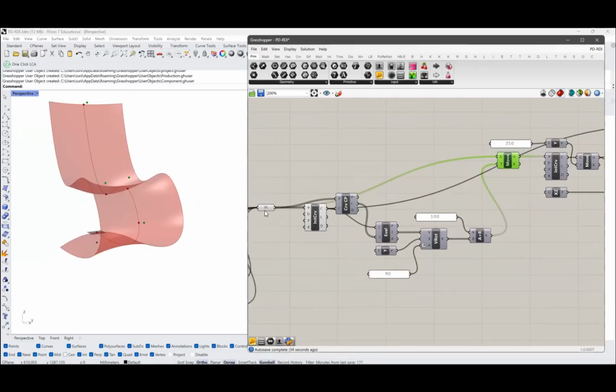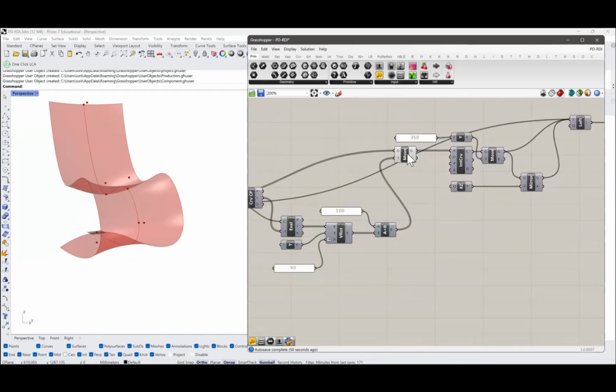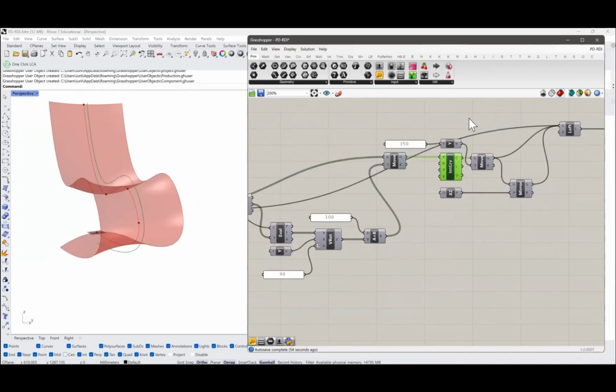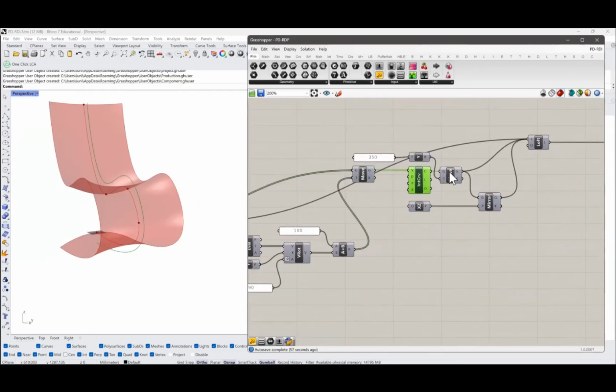So we take the same points and apply, for example, a deformation function to move them. Here we construct the vector, the logic behind how we can move each point. This small code at the bottom gives you the vectors for each point to move it. After the movement, we have another curve that we also move to the sides, and by this we create a lofted geometry.